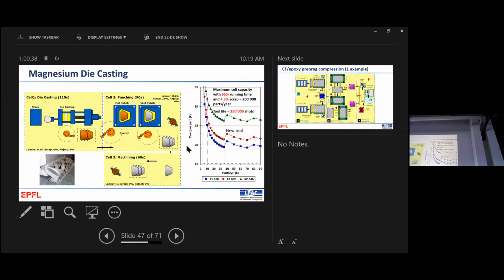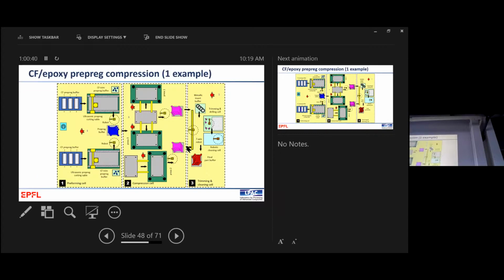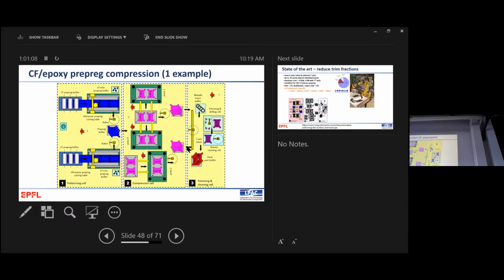Okay. We then said, well, how can we make this in carbon epoxy? And this is an interesting example because 15 years ago, the cure time for an epoxy pre-preg was around 10 minutes, whereas now it's come down to 1 minute 30 seconds for the pre-preg that's being used on the BMW 7 series. So you can then throw away half of this plant diagram because the kinetics of the material mean you don't need all this capex to mold all these parts. Okay, so that should go into your sensitivity study, reaction kinetics. Okay, your engineers, your scientists at base, always look at what's driving the assumption and look at it in detail.